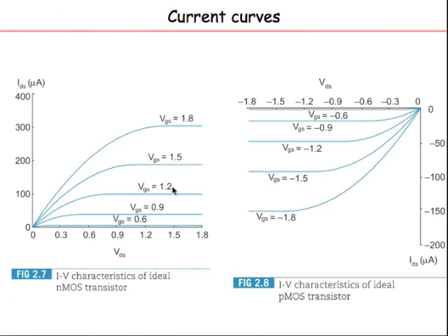We'll see that next, because the current also depends not only on the potential but also on what is called mobility. How mobile are the electrons or the holes? How mobile are the carriers? The hole mobility typically is lower, 2-3 times, but again it depends on specific technologies. Sometimes you can have hole mobility as good or better than that of electron mobility, but typically, at least in the kinds of vanilla processes we deal with, the currents in the PMOSs are a factor of 2 or 3 less than the currents in the NMOS for the same potentials you apply.